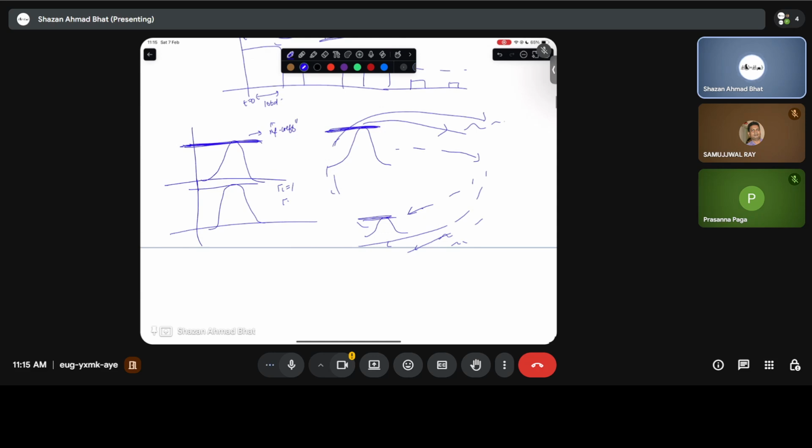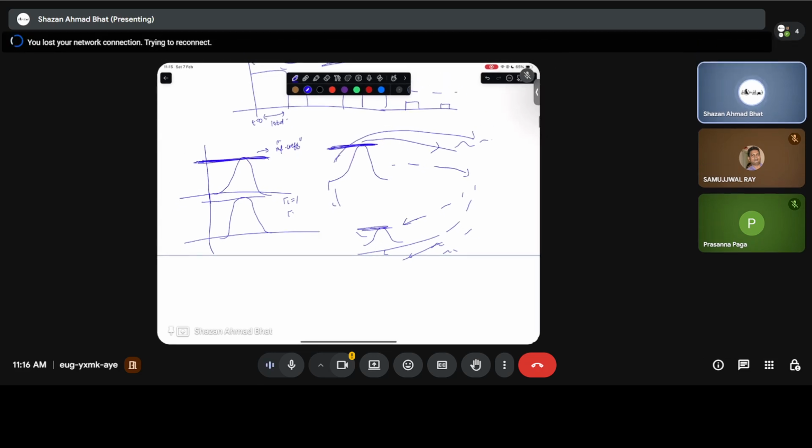So when you see a reflection coefficient, it can be -1, it can be +1. Okay, what does this sign mean? It indicates the phase. For example, you are given a pulse like this that goes towards the load, and if somehow the reflection coefficient is -1, which can happen by multiple causes, this indicates the phase flip of this particular wave.